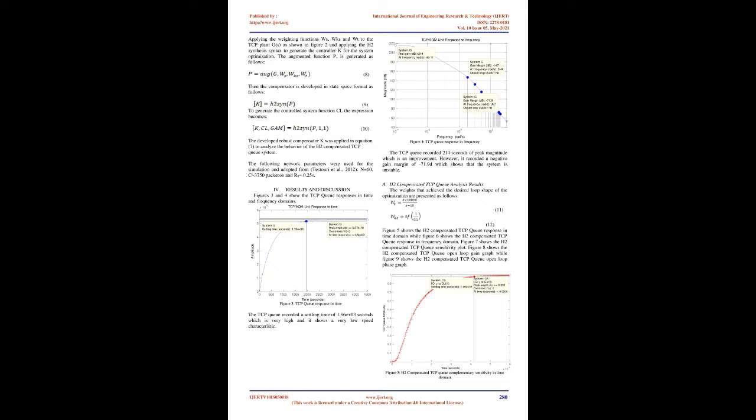C. H2 synthesis. H2 control theories have been active areas of research for years and have been successfully introduced to many engineering applications. It is a method of robust controller design which makes use of weights to form an augmented form of the plant to be controlled and produces a controller through loop shaping. H2 optimization finds a controller which minimizes the H2 norm of the closed-loop transfer function and internally stabilizes the system. The H2 norm of a signal is the mean energy with respect to the frequency.